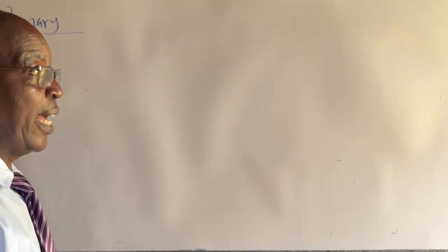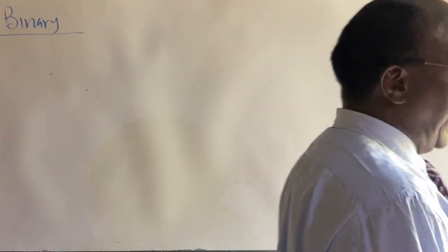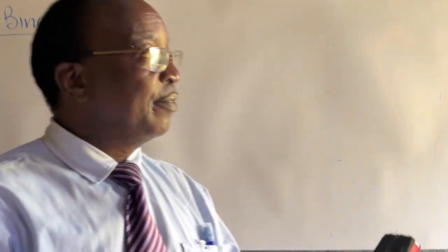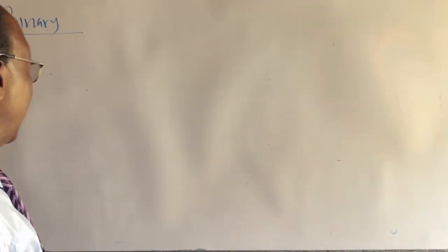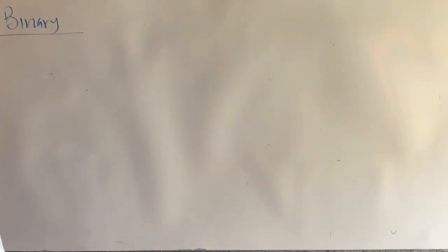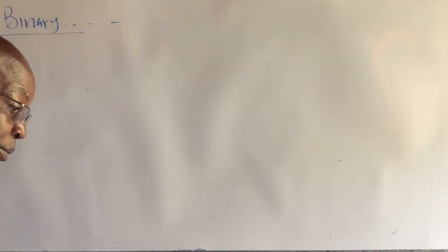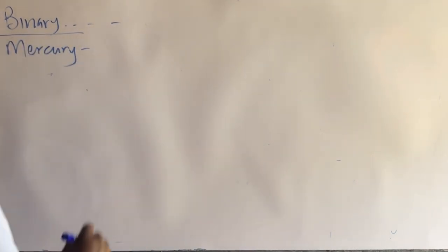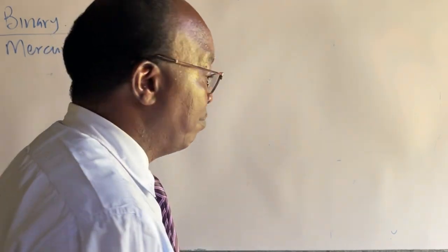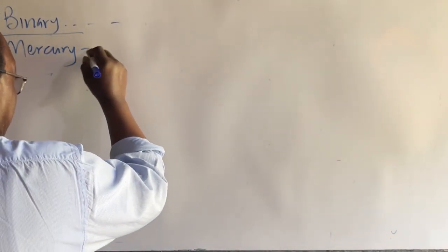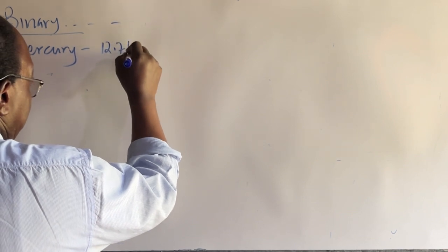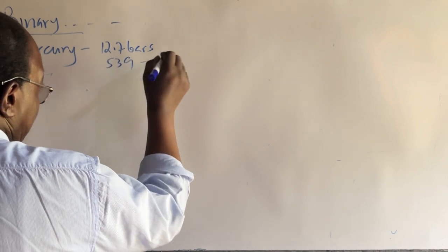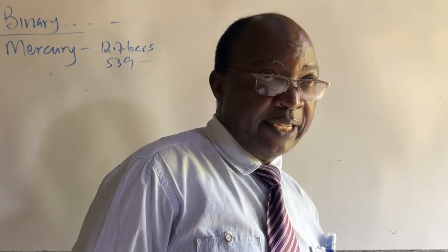So in that particular vapor circle, unlike the water and Rankine, which you had used earlier on, now we have mercury and we have water. And there were clearly two differences between these two fluids. That we had mercury, which has a relatively high boiling point at about 12.7 bars. The boiling point is about 539 degrees centigrade.